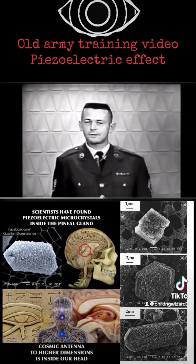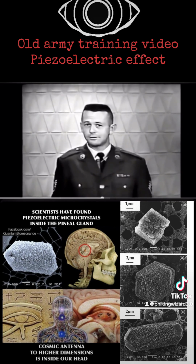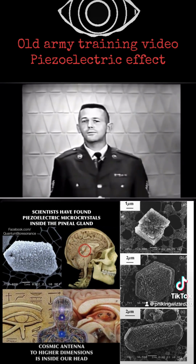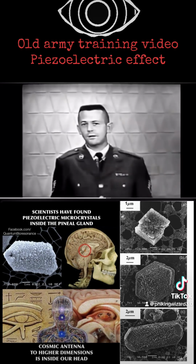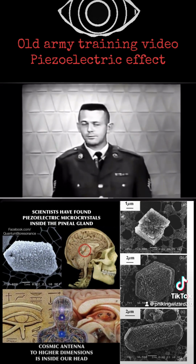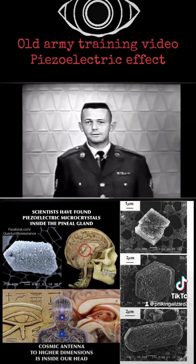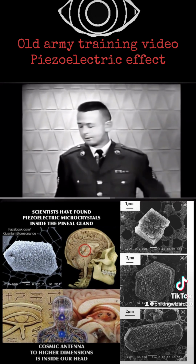lesson. Now, when an extremely high degree of frequency stability must be maintained, the crystal will be placed in a temperature oven. A temperature oven is nothing more than a thermostatically controlled container used to maintain the crystal temperature in its proper range. And in doing so, of course, we have a high degree of frequency stability.